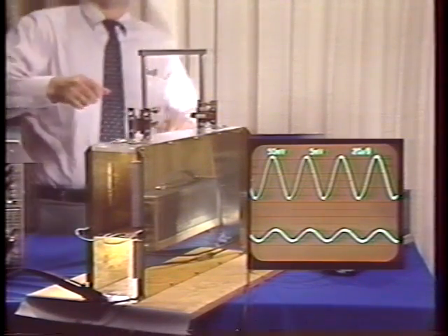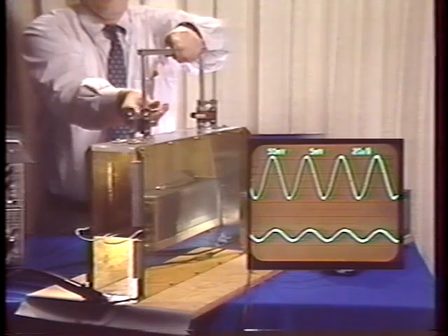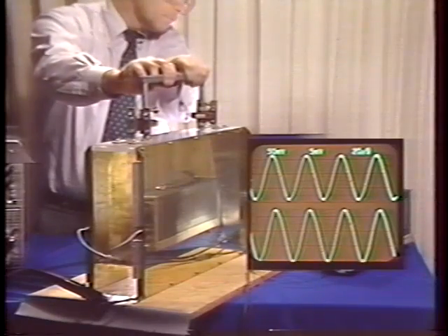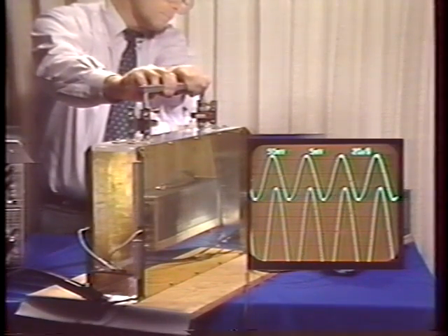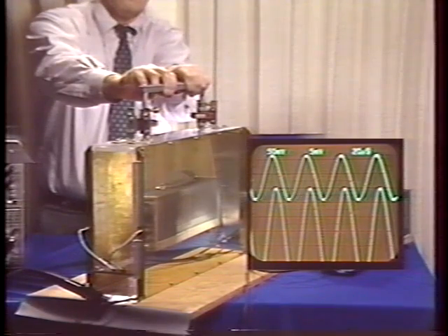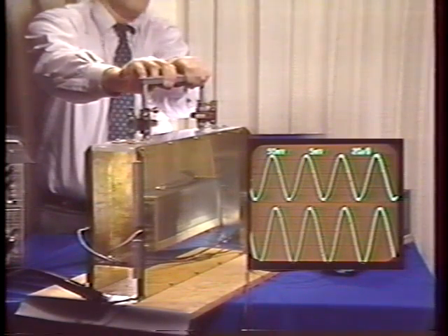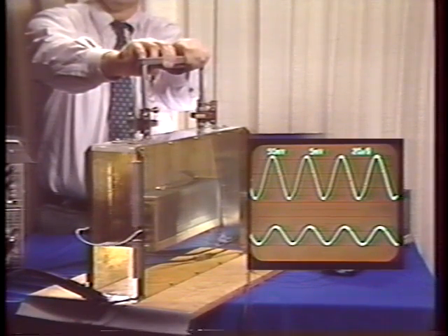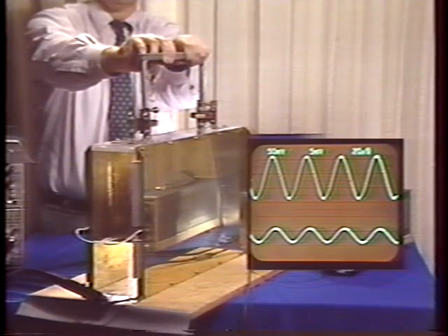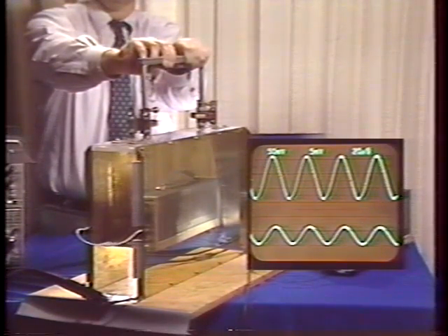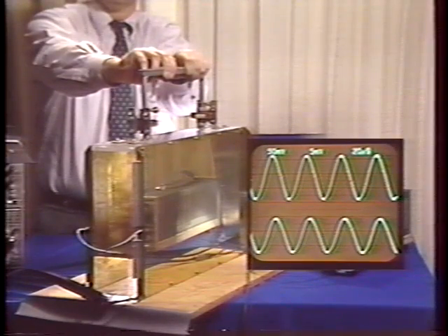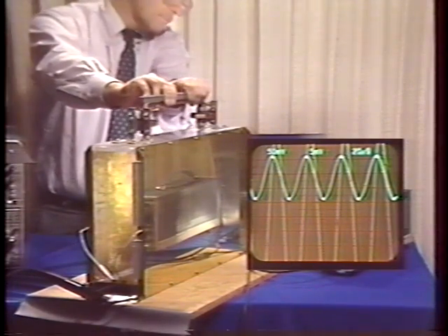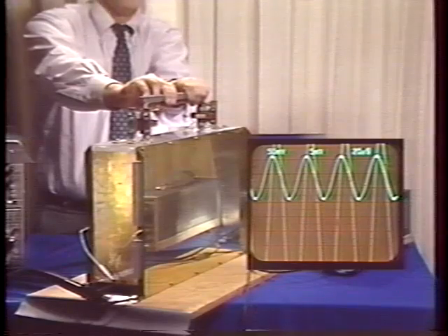Here's how the current induced in the lower electrode varies as the driving electrode is lowered. As the spacing is increased, again with the driving voltage essentially held fixed, the induced current decreases. As the driving electrode approaches the lower electrode, it increases again. With the electrodes this close, almost all of the current in the upper electrode is imaged in the lower electrode.